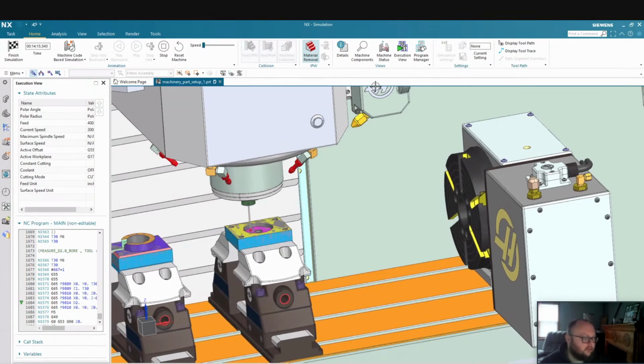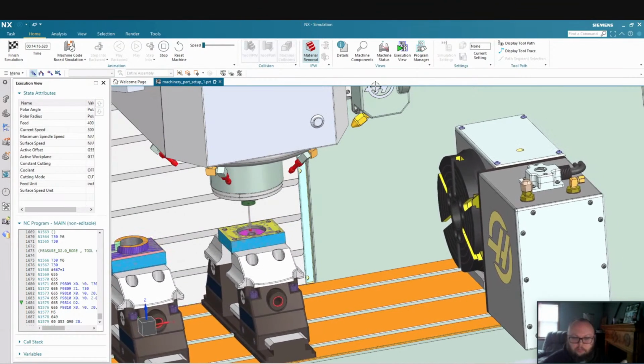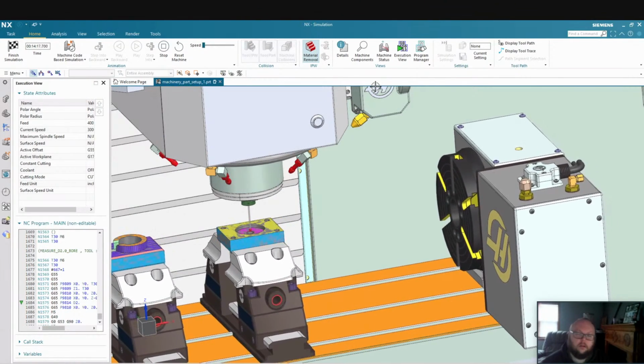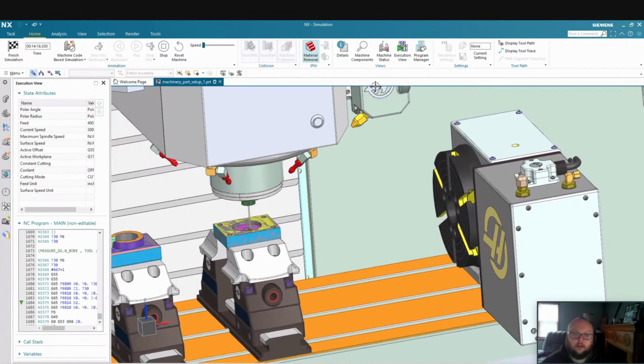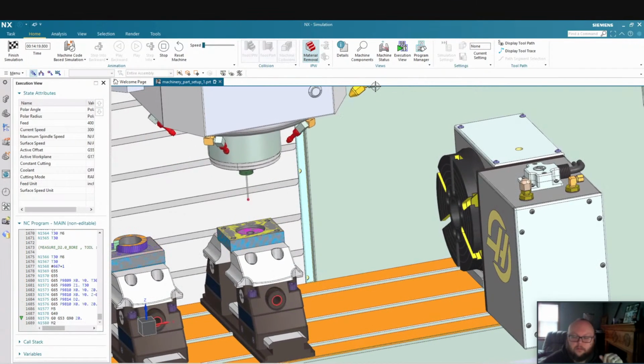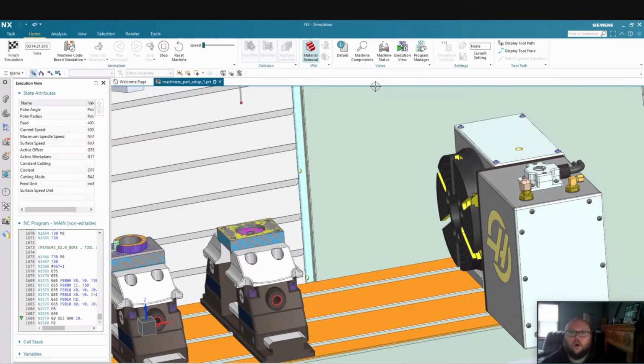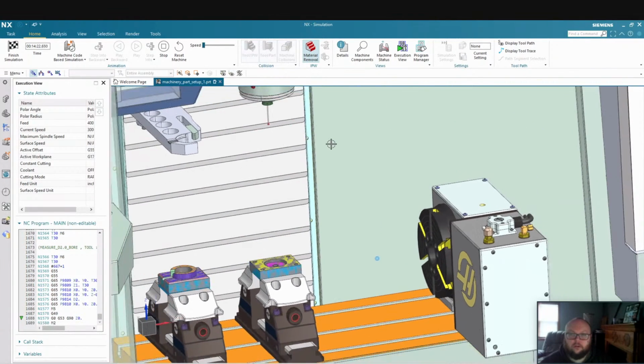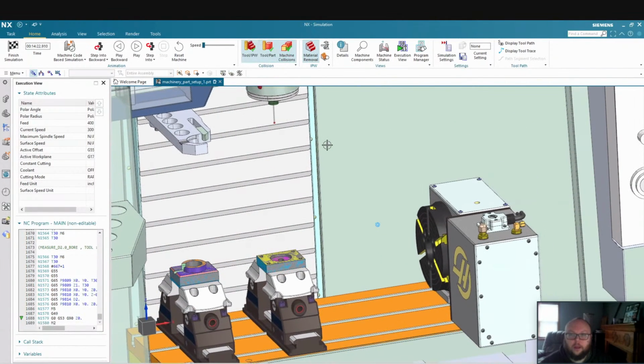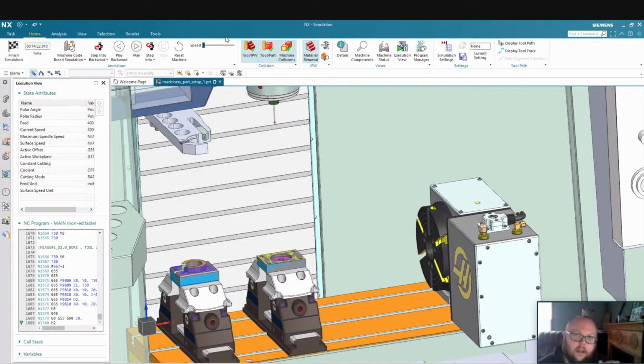So that brings up the topic: one, you can take these results and just look at them and say, yep, I'm in tolerance, I'm out of tolerance, I need to make some tweaks. Depending on what you really want to do, there's very little limit in how you can modify the use of the results of your probe routines. You can update cutter compensation values, so you're continually tweaking the cutter comp values to always stay in your target values for your part.